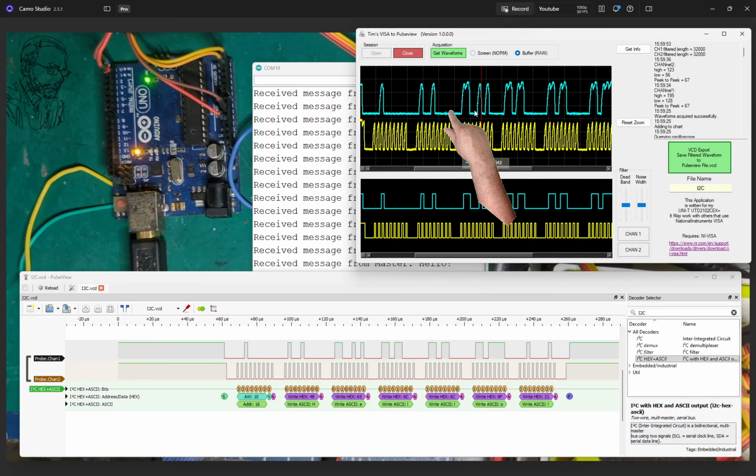It's not going to be the same as this, because UART doesn't rely on a clock, it relies on a speed that you set, and it reads each data pulse at whatever speed you've told it to read the digits on the line. Let me set that up and hopefully it'll come to light.